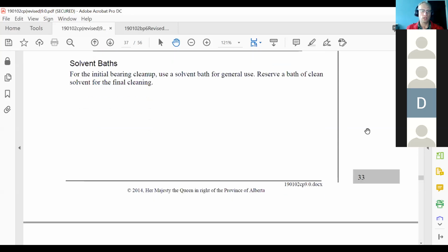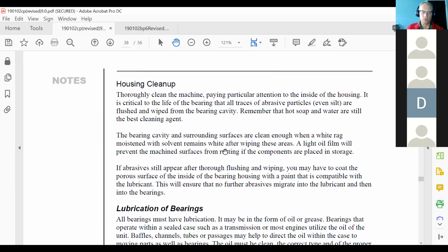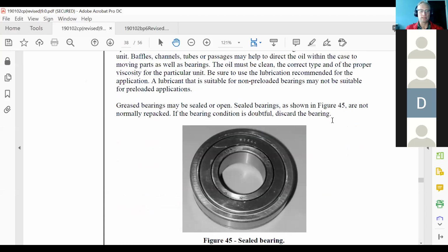So for your initial cleaning, a lot of times I just use a can of brake clean to spray the oil off to take a look at them, but you want to have a clean tank too. That's where you're not putting huge amounts of sludge in, all right? You want to try and keep these bearings clean. And that has to do with your machines. I've seen some really, really nasty looking solvent machines, or parts washers, or whatever the case may be. How we keep those parts clean is beyond me in some aspects, but we have to figure it out. We have to keep them clean.